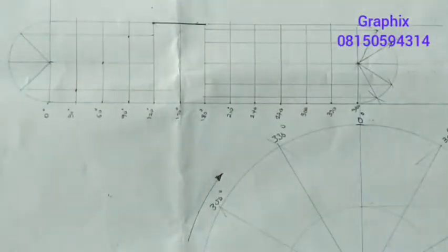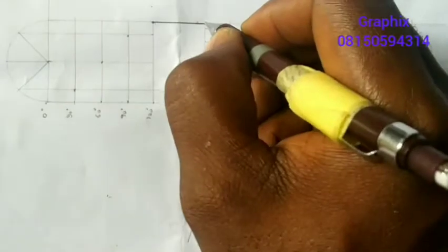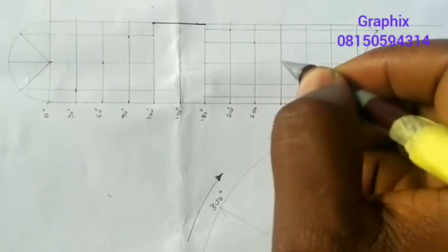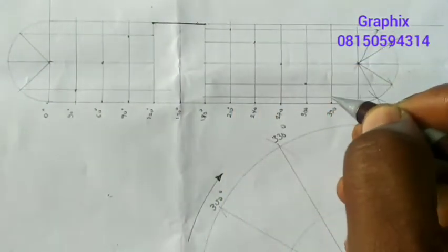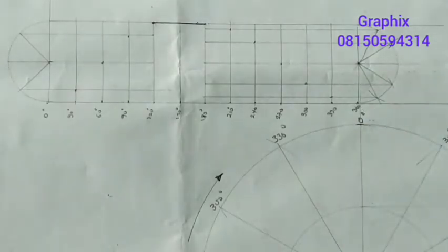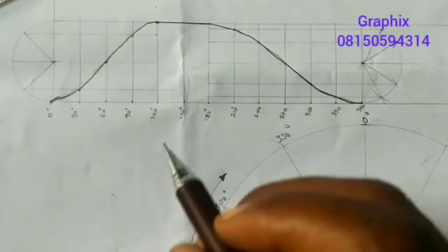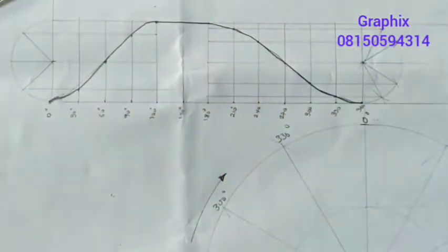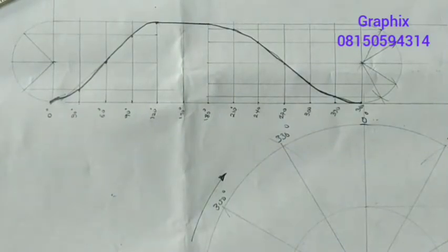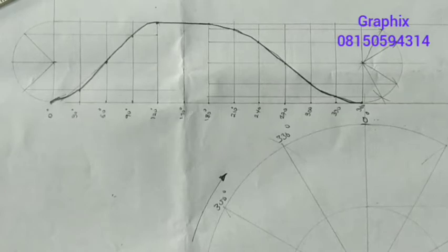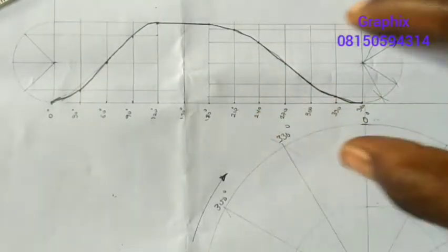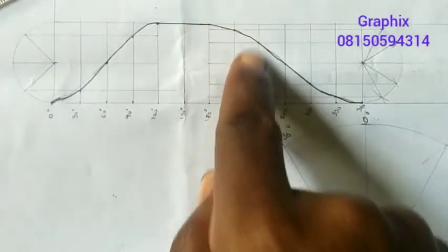So let's see, it's falling. So from 180 it starts falling down. From 180 it starts falling down until it gets here, right? So with the help of the French curve, you're going to join all these points together, and let's do that and see. So by joining it with a French curve, you're going to have an arc like this. Is that taken? So now let's apply this to our circle. So this is what we call the cam profile diagram, joining those points together.